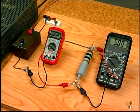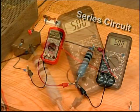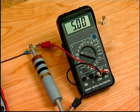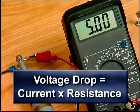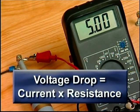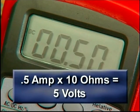If the loads are connected in the circuit so that the same current flows through every part, it is a series circuit. The loads are known as series loads. As the current flows through a 10 ohm resistive load, a voltage drop is produced across the resistor. The voltage drop is equal to the current flowing through the resistor times the value of the resistance. In this case, it is 500 milliamps or half an amp times 10 ohms or 5 volts.